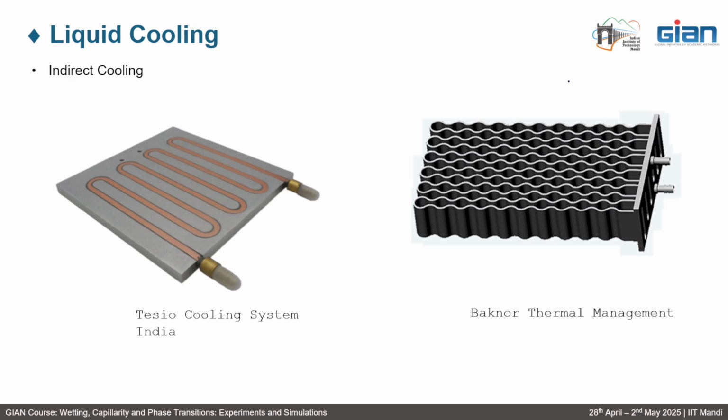Two-phase liquid cooling means that the phase change occurs, boiling starts, because latent heat is involved there. So at a constant temperature, it can take in a lot of heat. So let's suppose that you want to design a system for your phone, and it's given by the manufacturer that your phone chip will get damaged if it reaches a temperature of around 80 degrees centigrade. So what you would want is a fluid whose boiling point is a little bit less than 80 degrees centigrade. So when it reaches around 78, the temperature will not increase, but it will take in a lot of heat from the system.